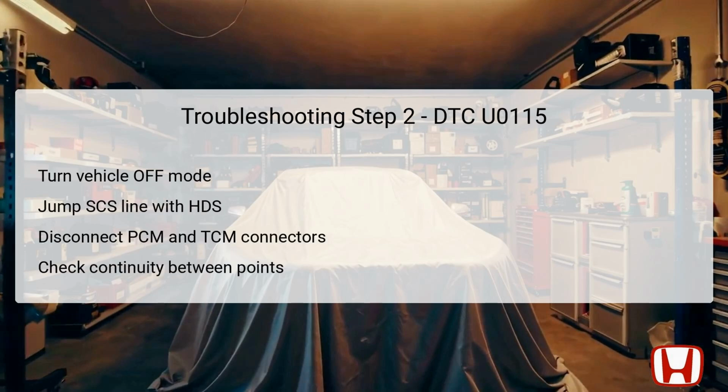In the second troubleshooting step, begin by ensuring the vehicle is turned off and in the lock mode. Using the HDS, jump the SCS Service Check Socket line, an important step for accessing diagnostic data. Allow the vehicle to sit for over 1 minute while maintaining this connection.